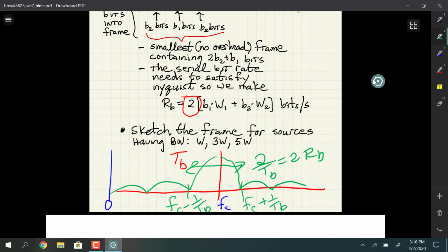So I kind of just gave you the answer to that, but that's what I'm looking for there. If you have to transmit that signal on a carrier, this is using rectangular pulse shapes, which have a sinc function for their spectrum. That's what we're talking about to support that transmission, the bandwidth that's required.